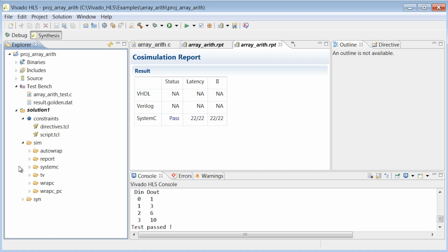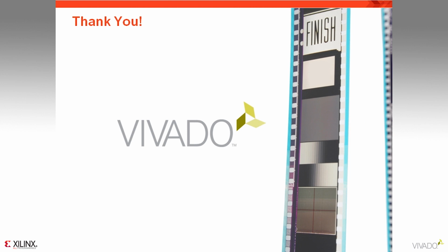The key message to take from this demonstration should be the importance of a self-checking C test bench. This allows both the C and RTL verification steps to be, as we have seen, a push button process when using Vivado HLS. This completes this quick take video on verifying your Vivado HLS design, and thank you for your time.